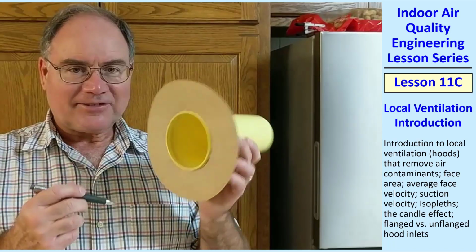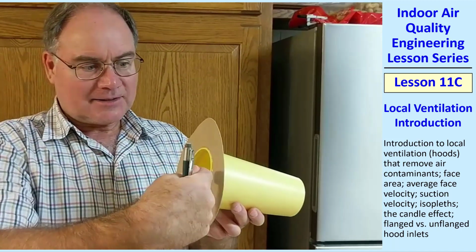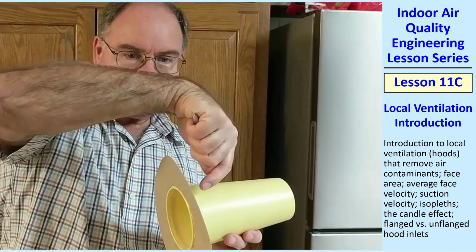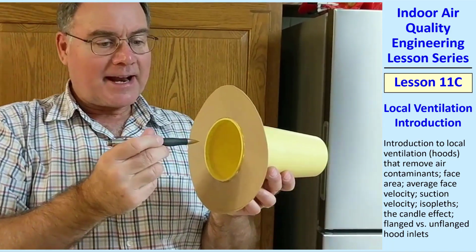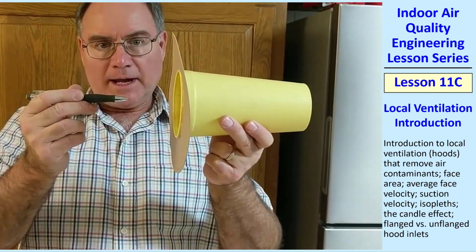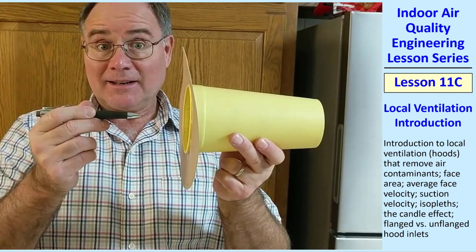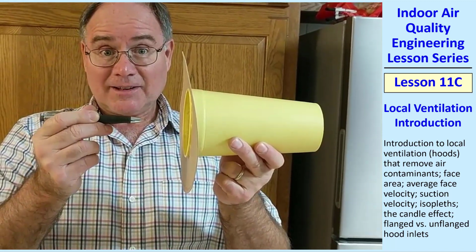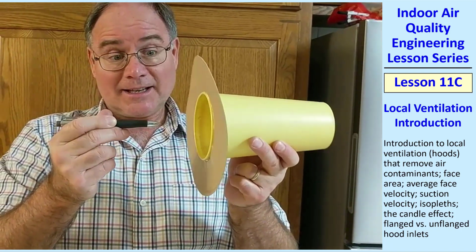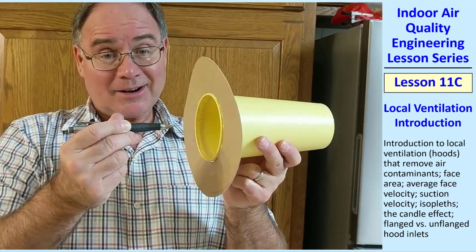Now if I add a flange at the inlet, so this is a round inlet with a flange, it directs the flow a little bit more parallel to the face. Flow isn't coming from the back. Now that helps a little bit. If I put my probe 1 diameter away at the center line, we now have about 10% of the face velocity. Improvement a little bit from without the flange, it was around 7%. This brings it to 10%. So it helps, but not a whole lot.